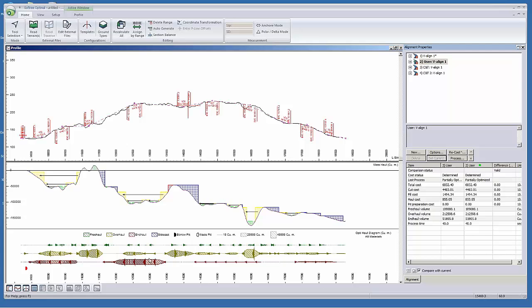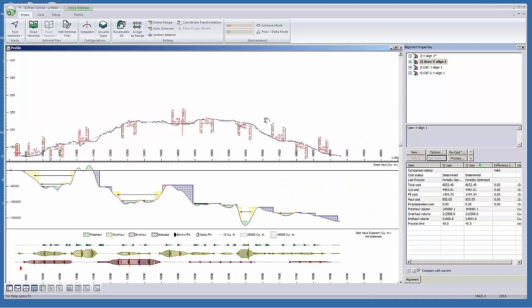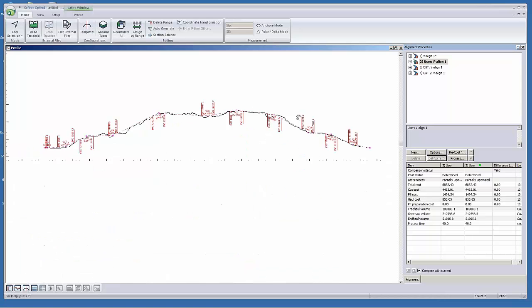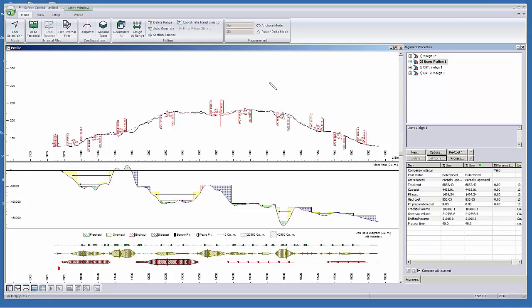And then this bar here is overhaul. See how it's been moving. And finally, the bottom one is end haul, and you can see that. And this table is based on optimal material movement, and you can print it out and bring it into a spreadsheet or copy it, paste it into a spreadsheet. So yeah, if anyone's interested, I could find out why this is so badly out of balance. I suspect it's the section spacing.